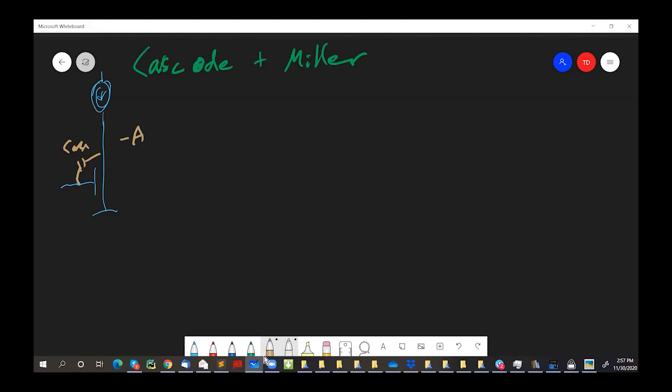So the effect of the CM is actually not just CM with respect to the input node, which has to charge up V1 here. It has to charge up not only the gate capacitance, which is to ground, but also CM times A capacitance to the output. Because when this voltage goes down a little bit, the output voltage goes up A times as much. And so the voltage across the capacitor changes A times more than it did before. And so for the input node to charge V1 to a particular voltage, it has to supply that much more charge. So is that clear?